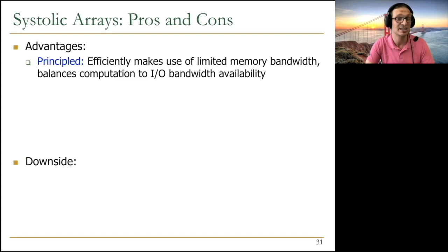The big advantage, well, there are two reasons why systolic arrays are highly advantaged: they're based on some principle, and they're also specialized. The principle is that it efficiently makes use of limited memory bandwidth. It doesn't need to go to memory for every single data item. It makes maximum use of one single data item by balancing computation to I/O bandwidth availability.